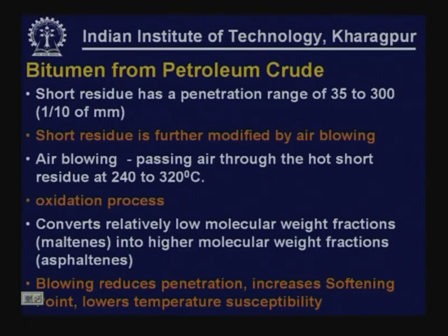that is, it makes the binder harder, increases the softening point, another term used to describe the consistency of the binder. It also lowers the temperature susceptibility of the binder. That means the properties of the binder are not going to change significantly with variation in temperature if these binders are blown.